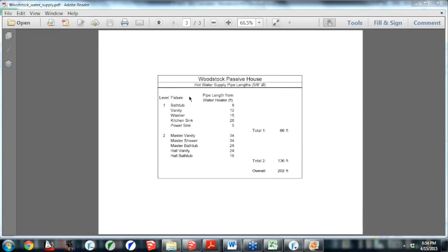I wish I could elaborate on how Revit can be used in WUFI Passive. It can be used in the same way as SketchUp. I don't personally have Revit, so I haven't imported it, but I do know quite a few CPHCs that work hand in hand with Revit and WUFI Passive now. If you contact me via email, I'll maybe put you in contact with someone that uses that often, to see if you guys can work together, or they can give you some hints on how to input that. We will have that up on our website soon too, from Fraunhofer, the specific details on how to upload that. But it's the same way that SketchUp works. Basically, there's a plugin, you assign the components different properties, and then you upload it.